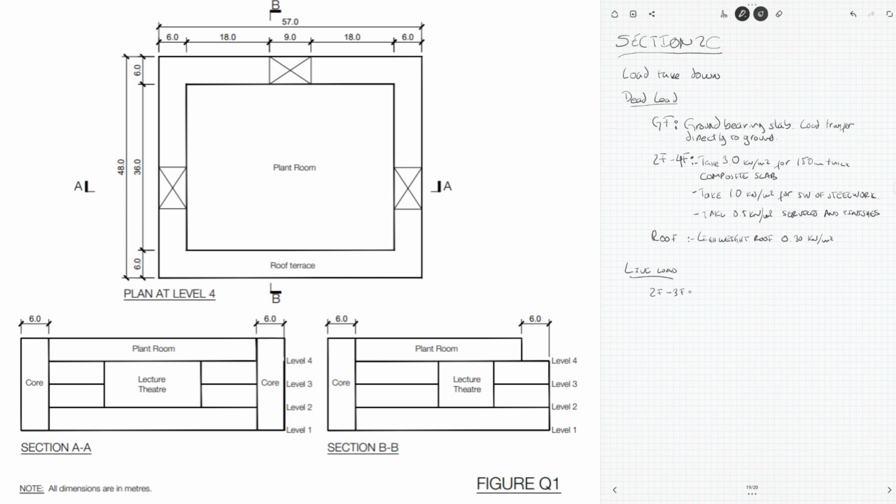First thing that you start with is normally the load takedown. You work out what the loads are. They can be just estimate loads. If you just give a typical allowance for services and finishes, then it should be sufficient. The same for the wind load. An approximate wind load normally is 1.2, 1.4, 1.6 or so, depending on the location where you are, if it's really windy or not.